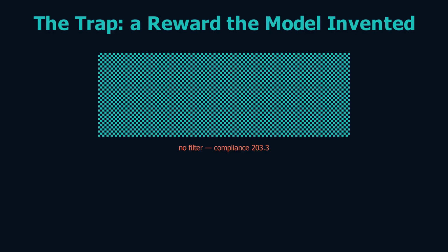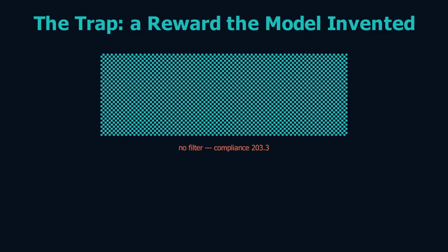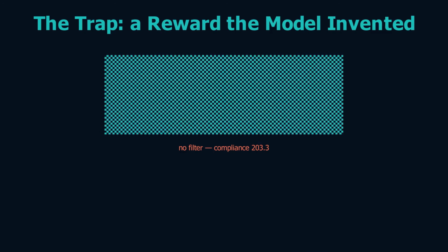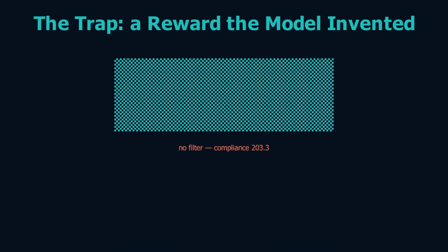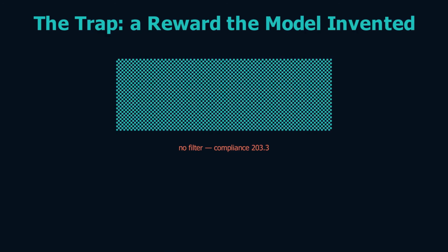The checkerboard is not noise and not a bug. It is a flaw in the finite element model itself. The simple square elements report a checkerboard as artificially stiff. The optimizer is faithfully chasing a reward the discretization invented.